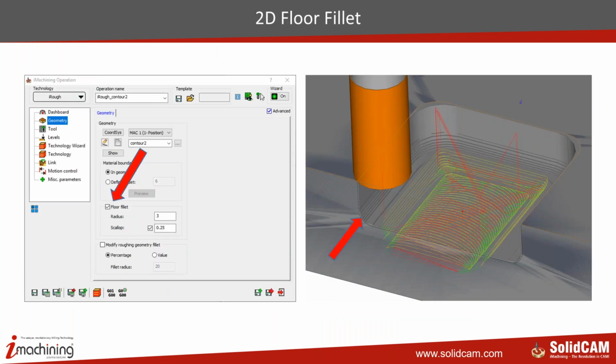Another very important function we have introduced in iMachining 2D is the 2D floor fillet. Suppose you want to use a flat end mill and you would like to introduce a fillet at the bottom without modifying the 3D model, where you have a sharp corner in the target model. Now this function is directly available under the geometry function. You can introduce the fillet, define the radius value, and define the scallop you would like for this fillet generation. Using a flat end mill cutter, you can generate the bottom floor inside the iMachining 2D strategy.